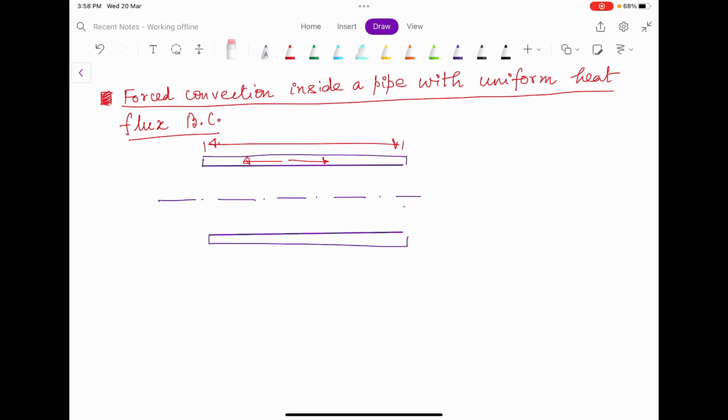Okay, so let us proceed with that, and we will neglect the effect of the thickness of the wall. When we consider the uniform wall temperature condition, obviously we will consider that the inner and the outer wall temperature, so if this is T1 and this is T2, we will consider that this gap is very small, because the conduction resistance is also very small here, because we consider a very thin wall case. Okay, obviously if the wall thickness is considerably large, comparable to the channel dimensions, then we have to consider that. Okay, so now this is our geometry.